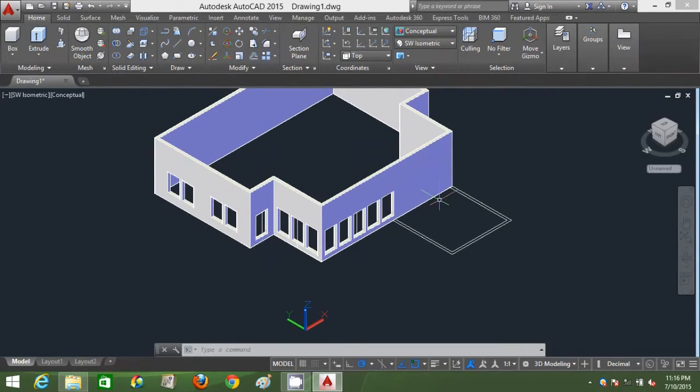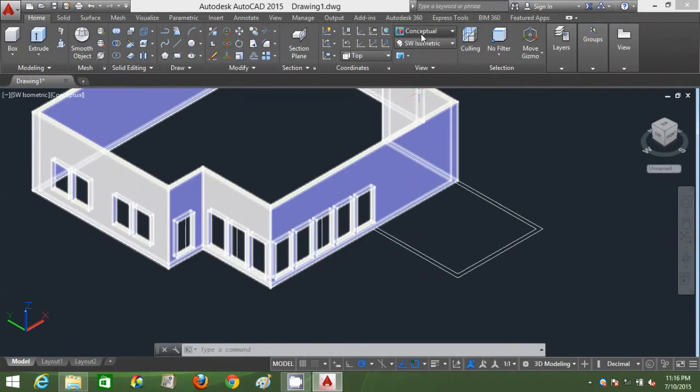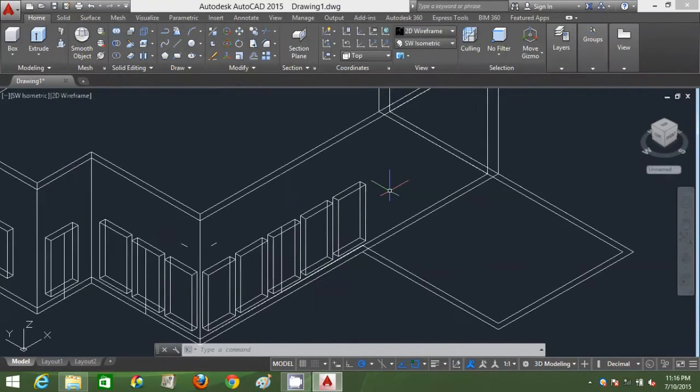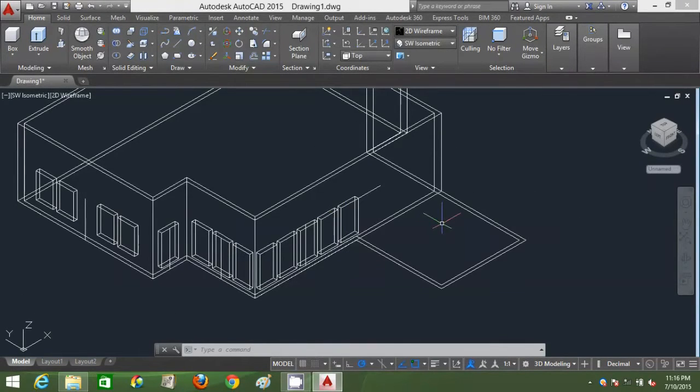So now I'm going to draw the door opening, the main door opening on the front of this 3D house. I'll just mark reference line 1300, because the distance between the door and the fifth window, the first window actually, is 1300, 1.3 meter. So I just mark a reference line there and delete all the balance lines. Go back to front view.